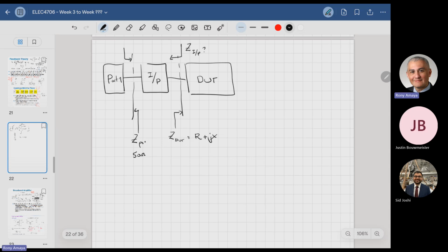Based on what you know here, 50 ohms, right? Because in 2501, I believe, maximum power transfer is achieved when the two impedances have the same value. So we'll write it down: maximum power transfer, when you have a source and you have a load and R_S is equal to R_L.